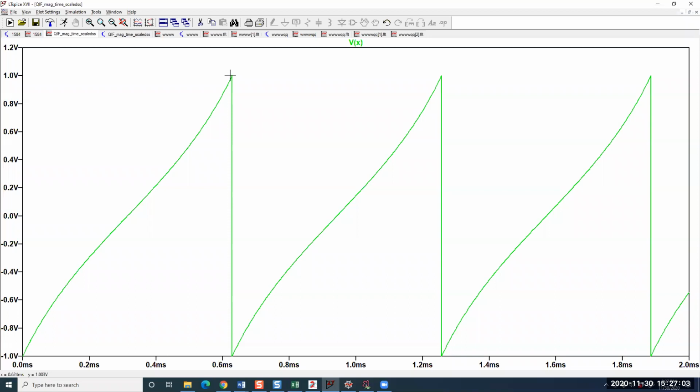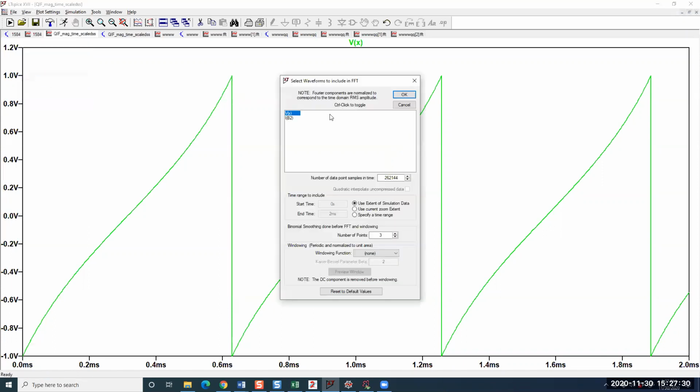All right. So how do I make sure that this signal isn't going over 10 kilohertz? Well, the smallest frequency will be the period, right? And yes, it's going from -1 to 1. And so maybe there's no DC offset, right? If it's even the way I have it. But the smallest frequency will be 1 over that period, right? But all I have to do is look at the FFT.